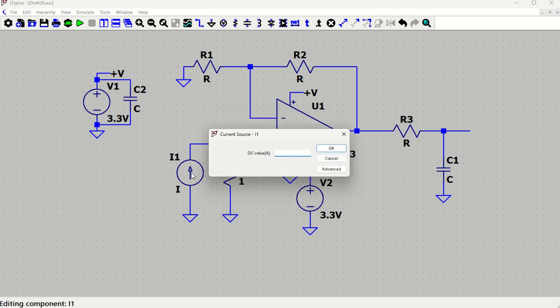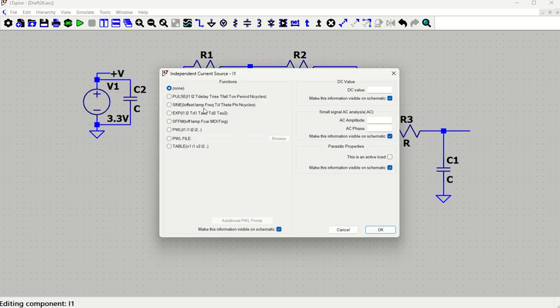And the current source we want to vary, right? So we want to vary a triangular waveform. In that case, what can we do? We can go to advanced and find a source called the PWL source, that is piecewise linear source, okay? If you press this, you have timestamps and you have the voltage that you need. So let us start with 0 time and we'll keep 0 voltage, or 0 amount of current, right?